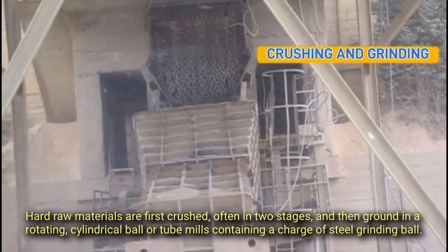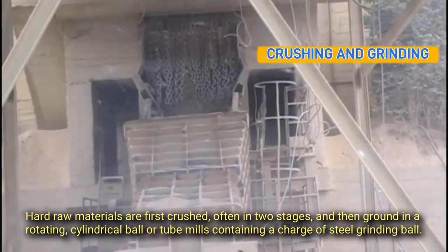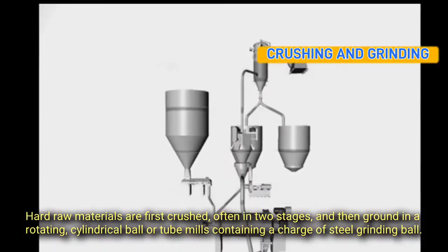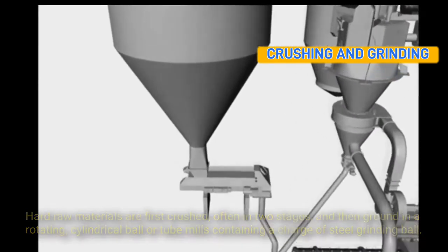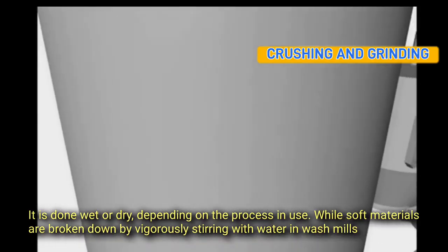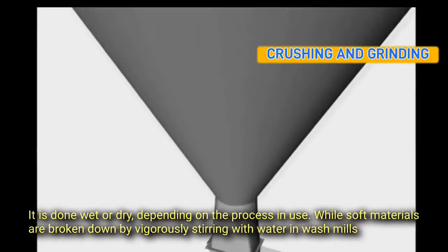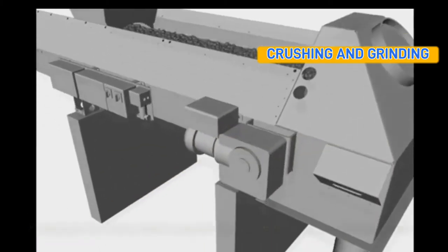Crushing and grinding. Hard raw materials are first crushed, often in 2 stages, and then ground in rotating cylinder ball or tube mills, containing a charge of steel grinding balls. It is done wet or dry, depending on the process in use, while soft materials are broken down by vigorously stirring with water in wash mills, producing a fine slurry, which is passed through screens to remove oversized particles.